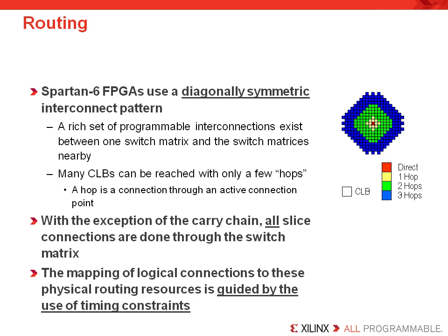The implementation tools select an appropriate routing that may include different kinds of routing resources. The solution that is routed is designed to try and meet your timing needs. To do this, it is important that you add timing constraints with the ISE design suite so you can communicate your timing objectives to the implementation tools. This will allow the software to choose the most intelligent routing solution to meet your needs. In fact, the mapping and placement of logic resources is handled by PAR, the Placement and Routing Utility.